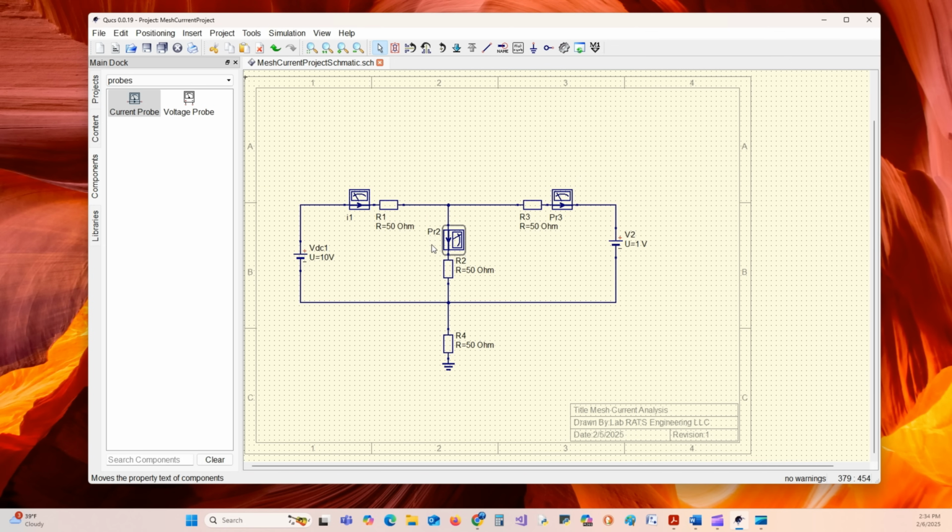Now this current here is a little bit different than you would think. So that's a good question for you guys. In the lesson we say that I2 is equal to R3 because loop 2 is the same current as in this loop that's going through R3. But I2 is not the same as the loop current going through the I3 because you have I1 current opposing I2 current. And that is the reason why it's I3 equals I1 minus I2, if you're wondering.